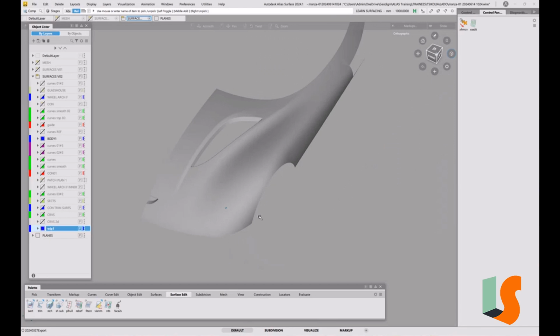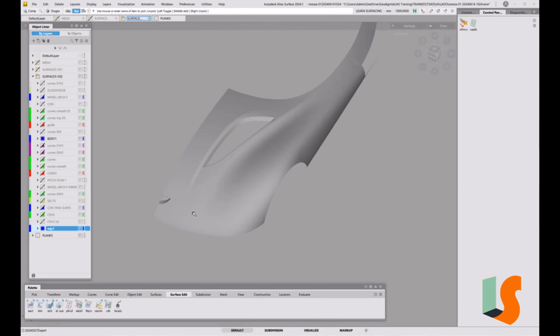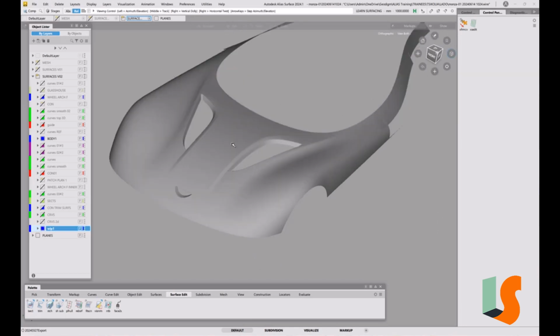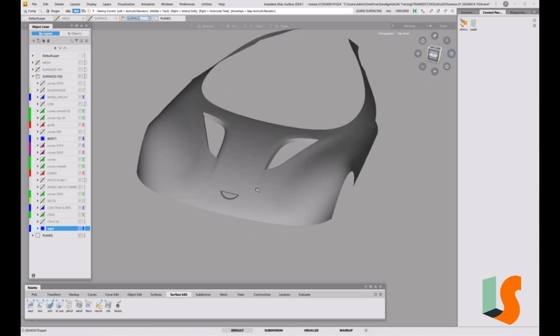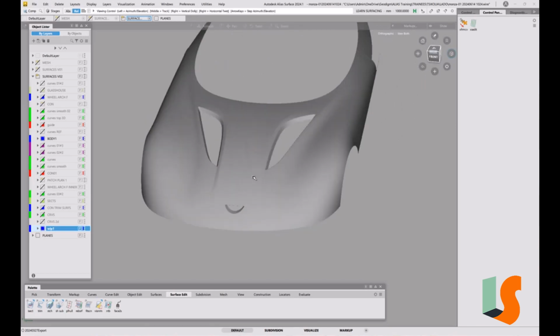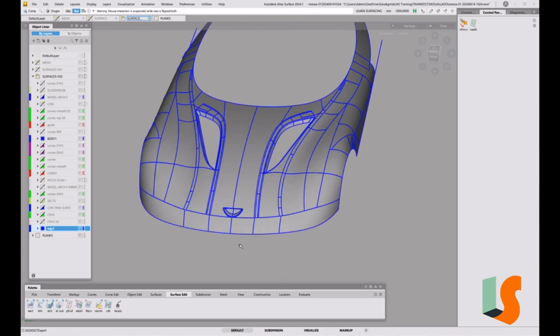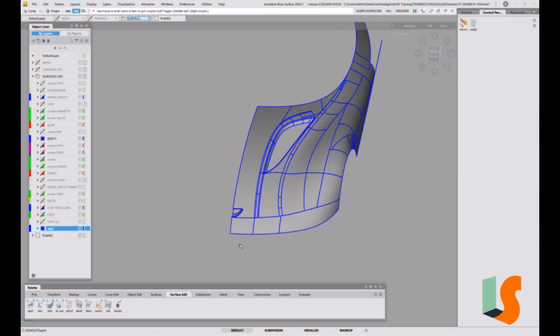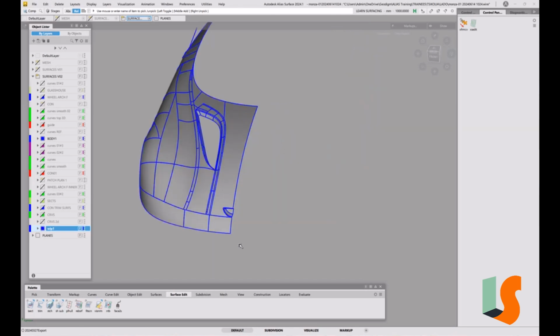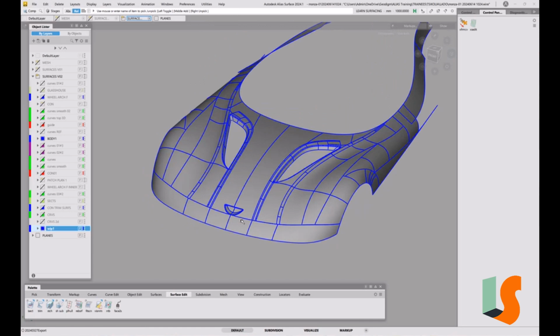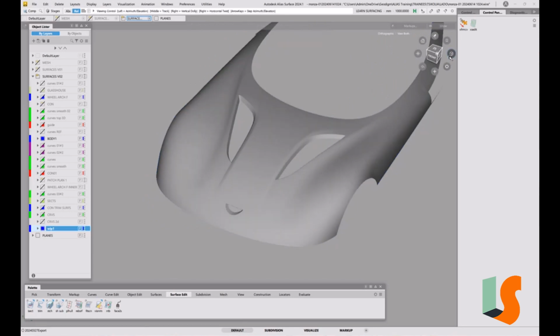And you know this, if you want to see what that all looks like, obviously I've got the other one to do, but I've run out of time today. But if we want to see what that looks like, we can press F8 and then you get the mirrored version. You can't work in F8, looks like a big face now. If I try and do anything with it, if I go and pick surface, it won't let me do it. So you have to pick F8 again to get rid of it. If for some reason you wanted just the mirrored side, you can press F7. I can't see any use in that whatsoever, but F8 and F8 again will just toggle between the half model and the full model, so you don't have to put symmetry on in the layer to do it. It's just useful to be able to see what that looks like in that view.